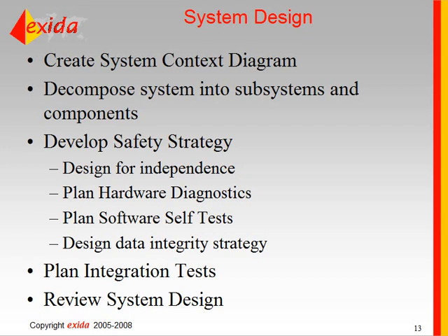Hardware diagnostics are planned at this point. Software self-tests are planned, so the software generally will have some tests to test the hardware, which are diagnostics, and it will also have tests to test itself to make sure it's running properly. You'll design a data integrity strategy at this point, which is the strategy for making sure that the data cannot be corrupted, or if it is corrupted, that it's detected.